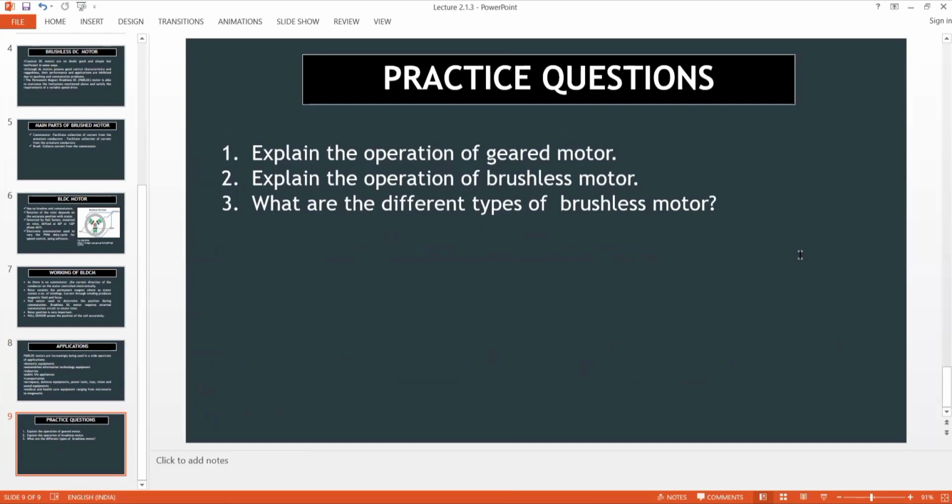So one thing is very clear, whatever the limitation we faced in DC machine, we try to overcome. And this can only be overcome if we are not using brushes and commutator. In certain cases, yes, we are providing the commutation circuit externally, but anyhow, we removed the brushes. That is the most important thing in this. And the second part, I just want to summarize. The second part, which is important in this brushless DC motor, is that we are providing the rectangular AC waveform so that it can be controlled electronically. I hope this is clear.